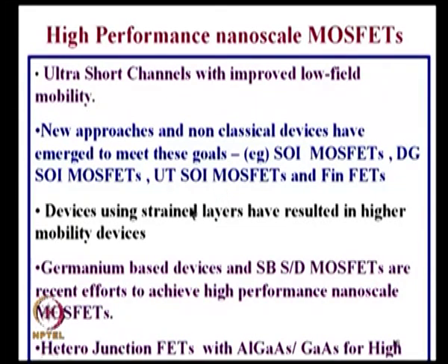How to introduce the tensile stress? I can deposit nitride on the top of the gate. That nitride has tensile stress, it will stretch it, elongate it. So, Intel has made some of these devices where they deposited low pressure nitride over the gate to touch the channel, so that electron mobility can be increased. Okay. And the hole mobility can be increased by compressing the channel.